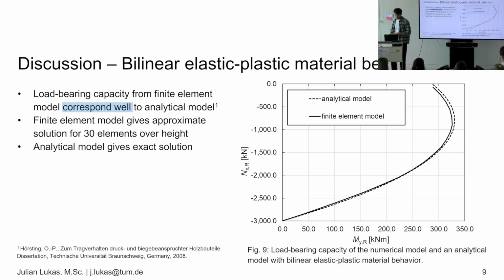Maybe you wonder why I don't use an analytical model after all, also for the nonlinear analysis. This is at the end really hard to implement, because for the bilinear model I just have two straight lines, but when I get a curvature into my analytical model and I want to model at the end the loss of the E modulus, it's hard, because I need to find some way to derive or integrate that, and then I also need some lines which have a polynomial form. In that case, it's better to use finite element modeling, I know from experience.